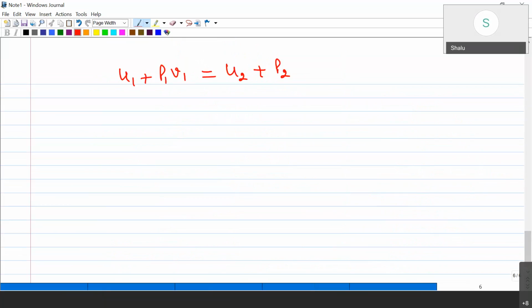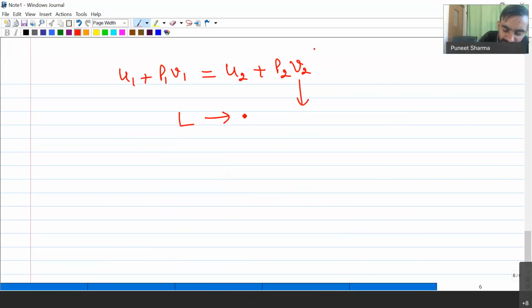So, sir, is there any change in the state? Yes, because specific volume is increasing, majority of the time we will find that in a throttling device, liquid partially changes to vapor phase. In our subsequent lectures, while discussing vapor compression refrigeration systems in applied thermodynamics, I'll be telling you about the throttling process in more detail.